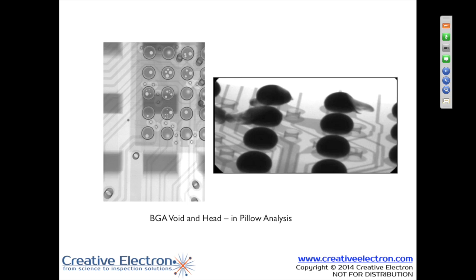X-ray, again, for BGAs, as well as for all electronic components, is not a silver bullet. Just because you buy an X-ray machine and put it in your building, all your process problems aren't necessarily going to go away. You have to understand what you're seeing in the X-ray, and then you have to have the ability to compare that information. So the database concept of the X-ray system becomes key.